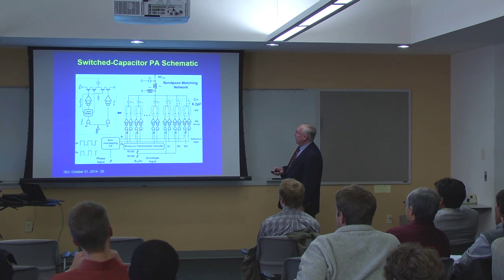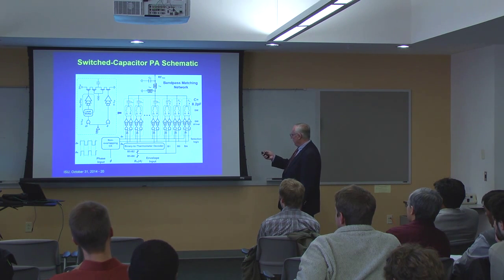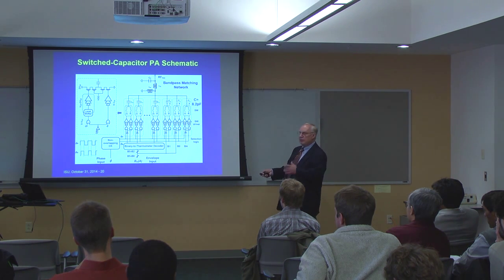So again, that's an amazing structure. There it is, a power amplifier with no amplifier in it. You've got the tuning network up here, the switch capacitors here, switches here, buffers to drive the switches here, and information to convert the binary code to thermometer code and deal with the amplitude information and so on. So it's a pretty simple structure.